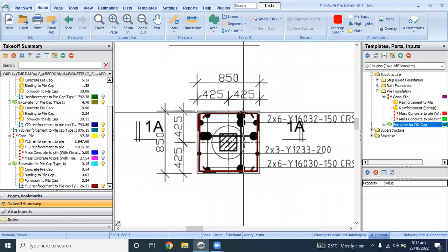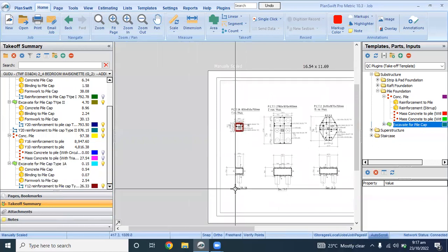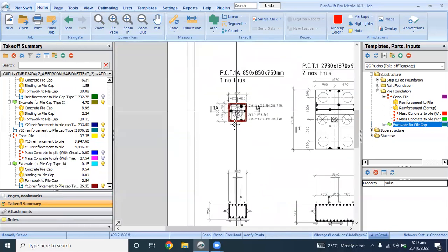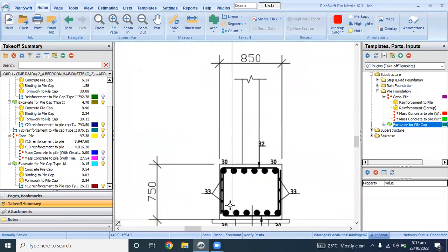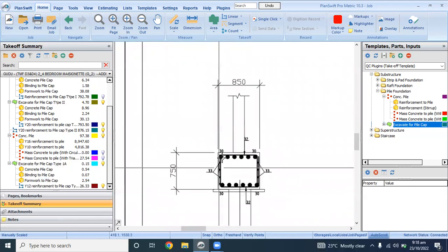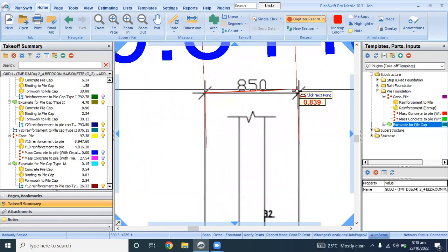So what of these internal ones? Mind you, the way you are seeing this internal one, that's not how it's going to be done on site. There's going to be bend, as being shown on this section here. So as you are taking the measurement here, you have to add this bend. So let me check whether this scale here is correct.